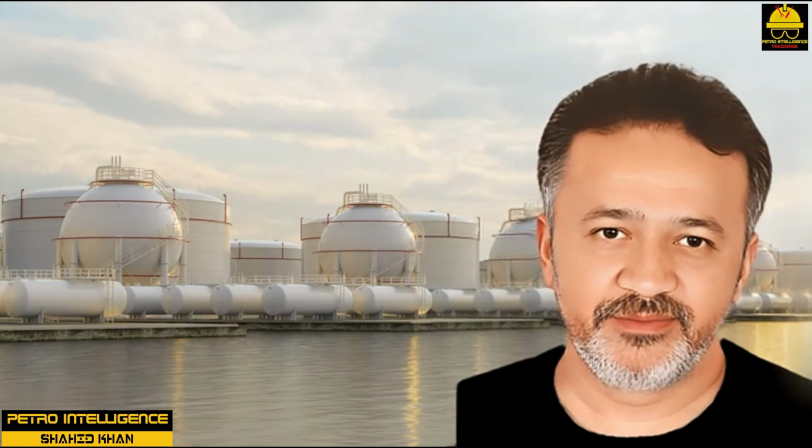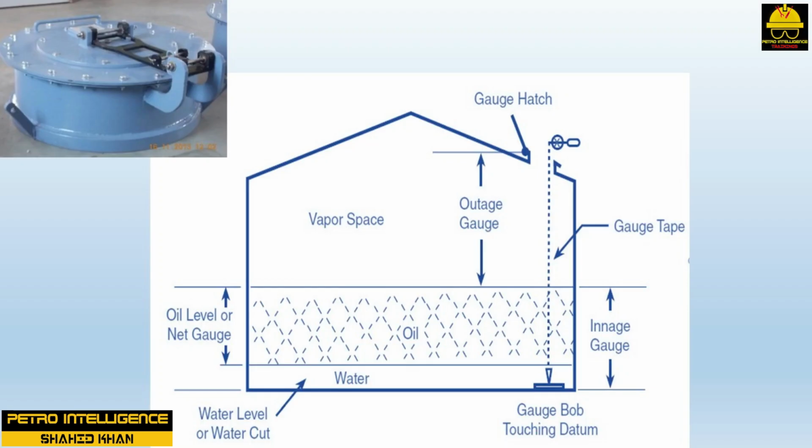Gauge hatches. Gauge hatches, as shown in the picture, are provided in the roofs of atmospheric tanks to enable the contents to be measured. A secondary function of a gauge hatch is to provide some emergency pressure relief. Except when they are in use, gauge hatches should be kept closed to prevent loss of vapors, fire hazards, and entry of rainwater. Hatches should not be weighted or otherwise restricted from opening because restricting their ability to open eliminates their function as a pressure relief device.